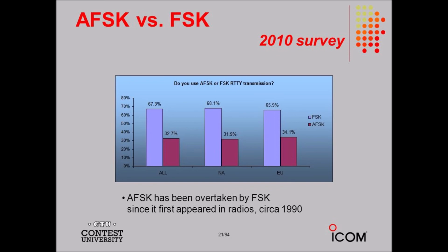We call this mode narrowband FM, NBFM. The bandwidth of an NBFM signal roughly equals that of an AM signal containing the same modulating information. In FM hi-fi music broadcasting, and in some other applications, the deviation exceeds plus or minus 5 kHz, giving us a mode called wideband FM, WBFM.